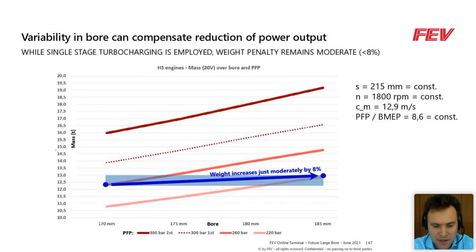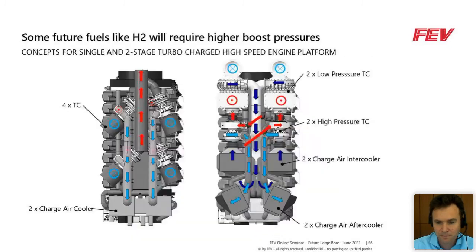How can we realize this in practice? One possibility could be that we do a modular casting architecture where we can modularly change the cylinder domes or the cylinder cores, or in future we could also think to introduce water jacket designs like on medium speed engines, in the high speed class. So to exchange bores in a more modular way.